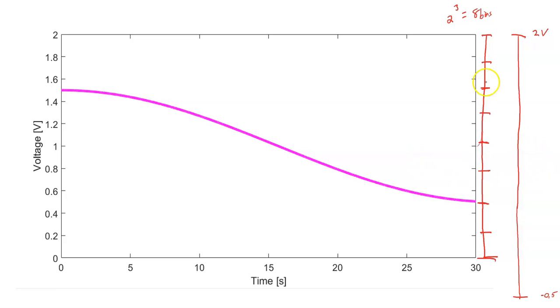So let's say this one had an even smaller number of bins. This one's a 2-bit converter. In practice, we would typically see 8 or 12 or 14 bits typically. Sometimes as low as 6 bits, but we're just going much smaller than we would normally see so that the effect is much greater and easier to see. So this is a 2-bit converter.